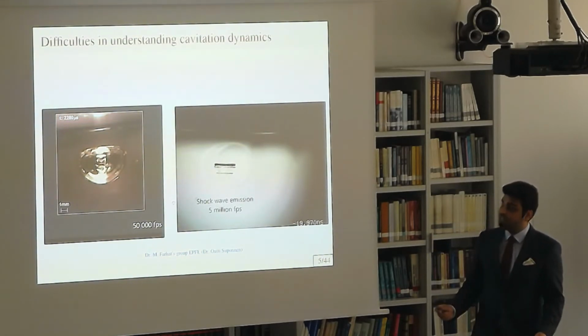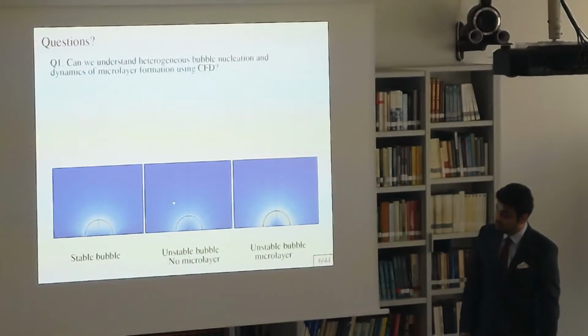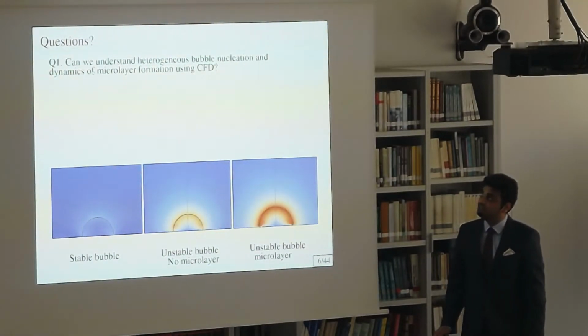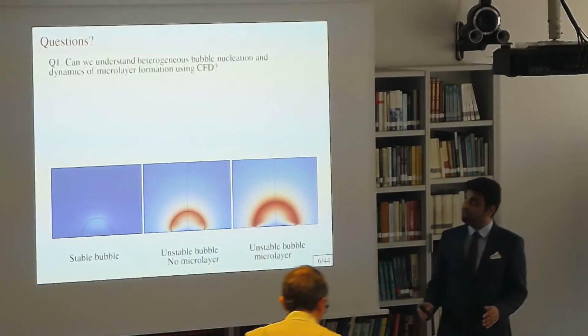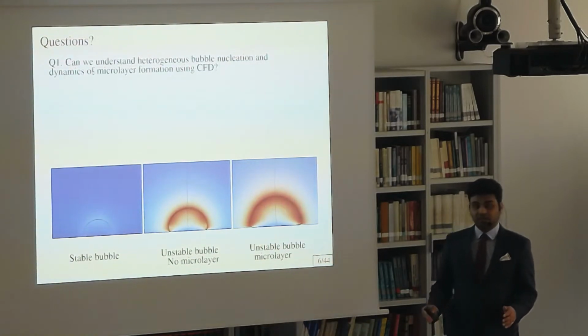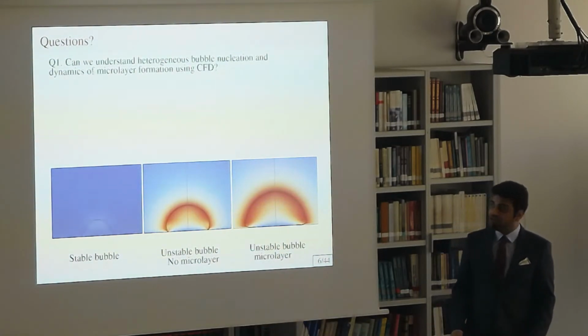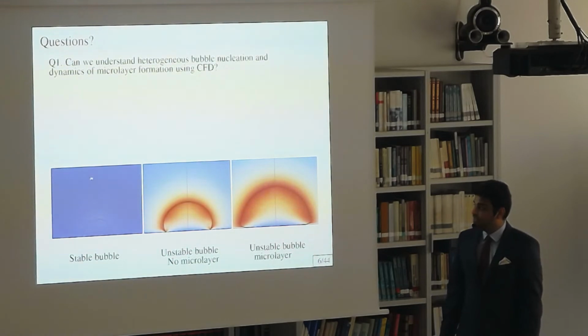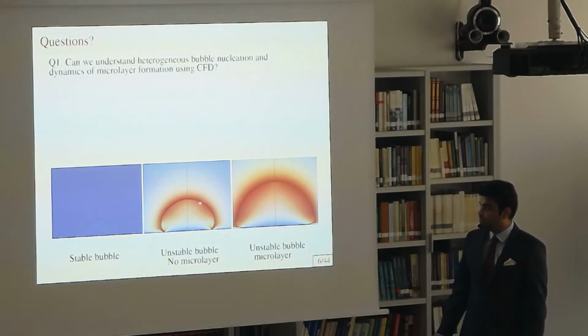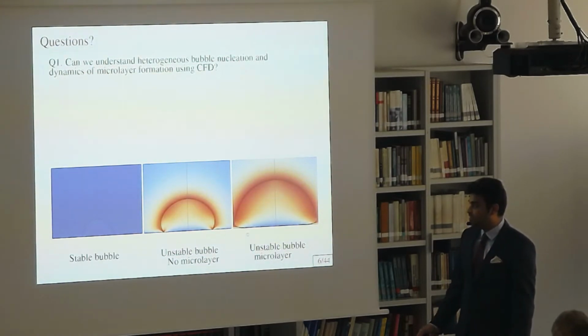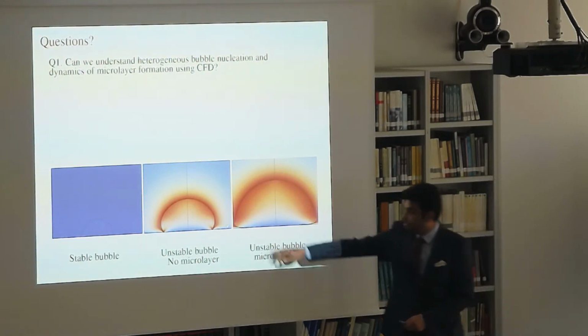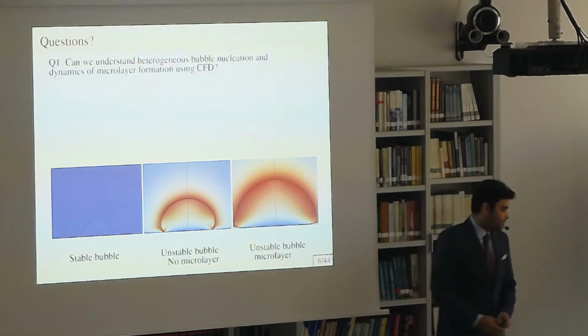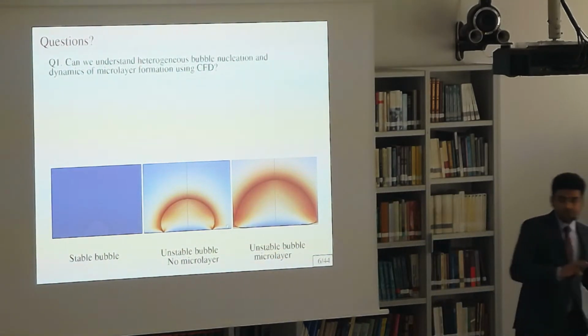What are the questions that we want to address in this PhD? The first question that we ask is, can we understand the heterogeneous bubble nucleation and the microlayer formation using our CFD model? We want to understand when does a cavitation nucleus grow into a large bubble, and when does it form a microlayer, which is the layer of liquid that is trapped here in the middle of the bubble and the solid.